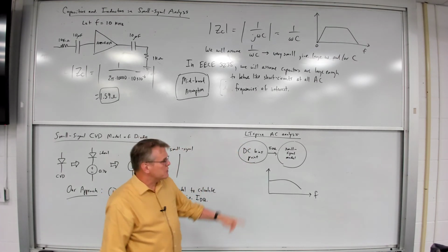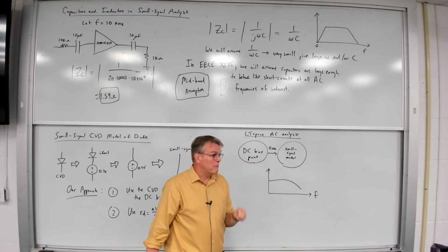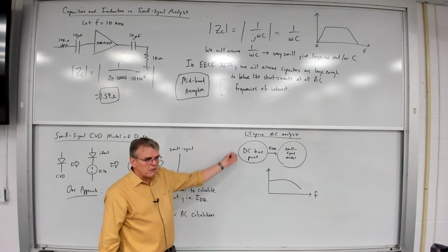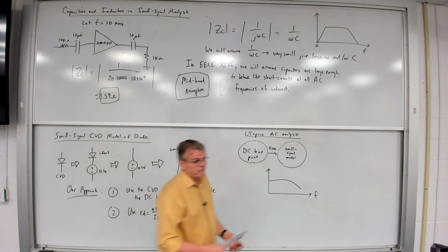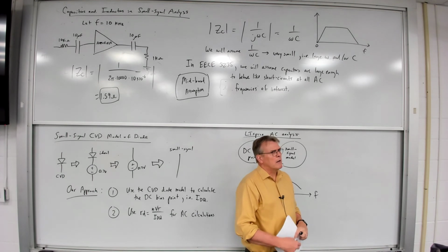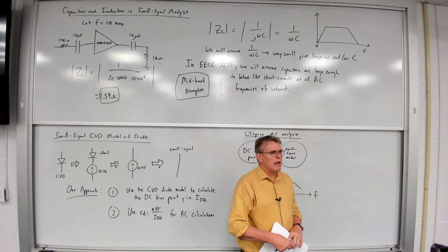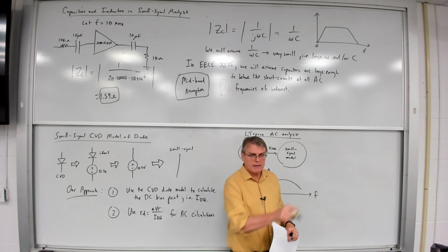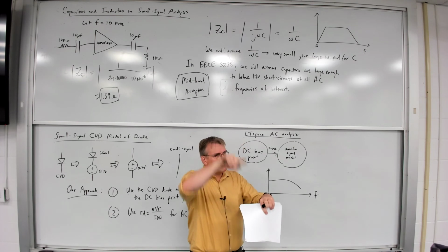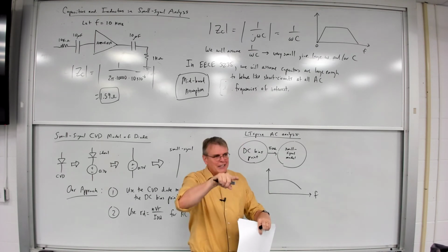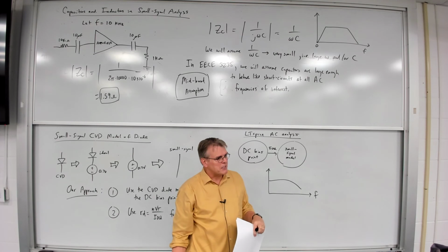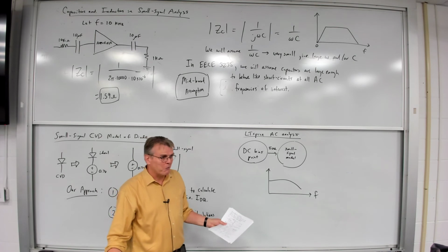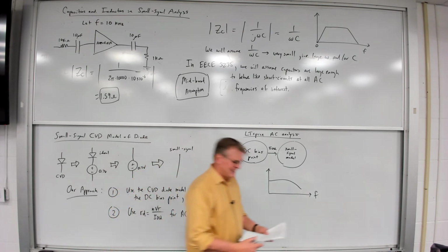We are assuming unity here, but that's what I'm saying. The hand calculations versus what LTspice will tell you, depending upon the model, can be different than what you expect, because not all of those values are going to be the assumptions we are making in this class. In fact, I think in one of the labs at some point in the future, you're going to be asked to actually calculate n, according to what you measured off of the AC versus DC plot on the Elvis units. So you can actually calculate that and see, is it really equal to 1? Well, you'll find it's not really equal to 1. Okay?